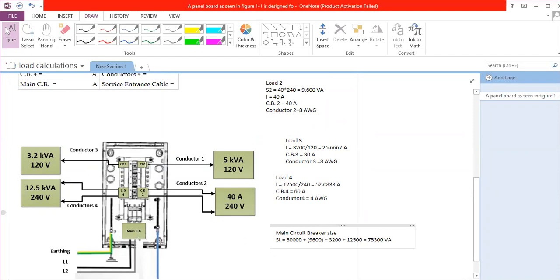I cannot say, well, this one is 40, this one is going to be another 4, this is 45, this is 40, this is circuit breaker 30, this is circuit breaker with 60, then I calculate the whole circuit breaker currents and then I will add it to circuit. It doesn't work like this. The main circuit breaker at the end is connected to different loads. So we have to calculate the load. This is rule number 1 in calculating the circuit breaker size.